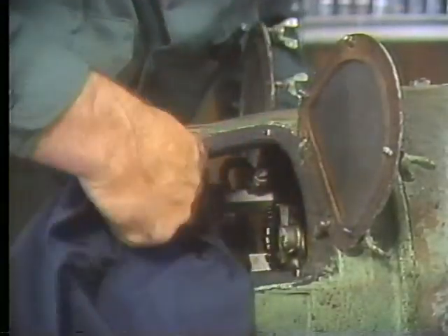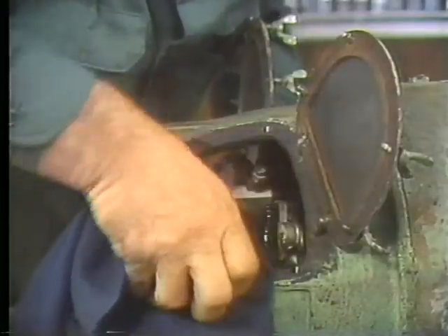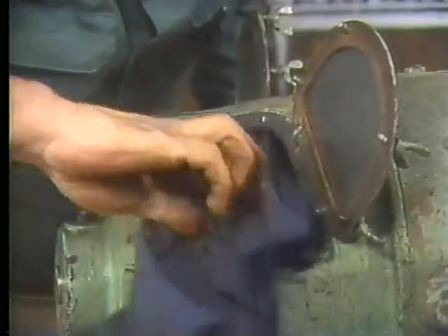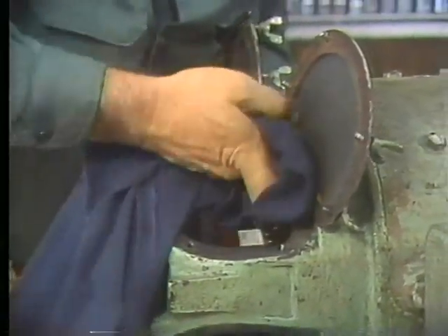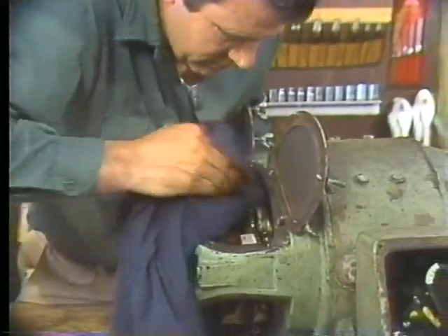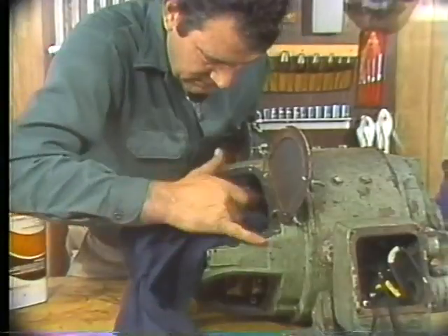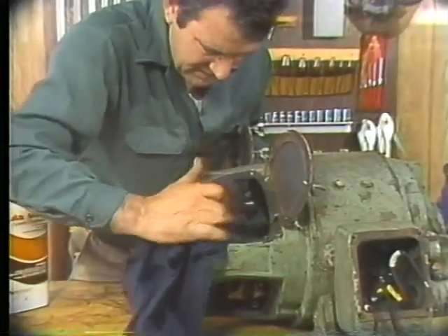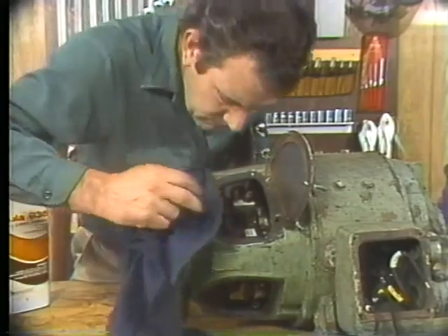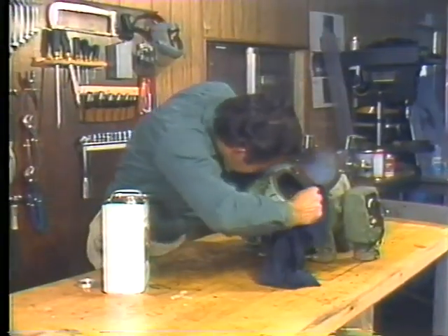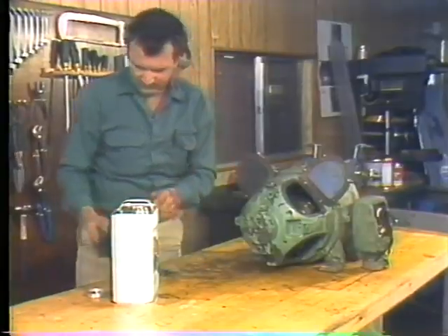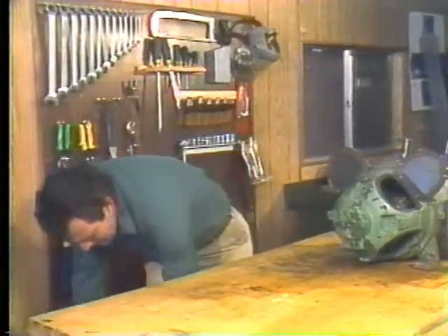Be sure you observe the safety precautions established in your plant for using cleaning solvents. Pay particular attention to the brush holders and the brush rigging, and be sure to clean the commutator thoroughly. Make sure you get the area between the segments too. Be very careful when you're using solvents on the commutator though. Do not remove the brown coating from the commutator segments. That's there for a reason, and we'll talk more about it later.